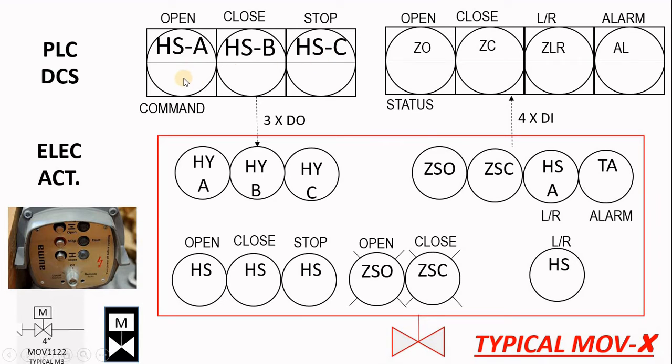That means when you send the open command as a pulse, the valve will start to open until it is 100% open. But if it receives something in between, while it's still traveling, such as a stop signal, it will cease at that moment. So you can open the valve to 20%, 25%, 50%, whatever it is.